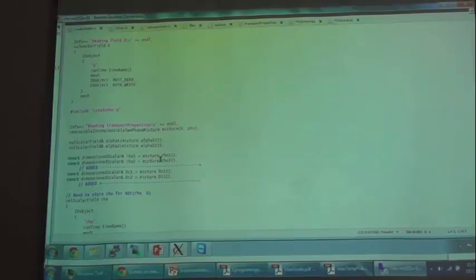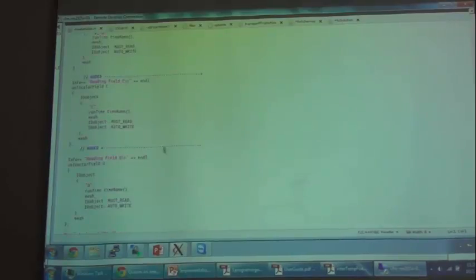So these are the properties that you have to basically add to the existing solver. It would already have provision to access rho 1 and rho 2, which is the density of the individual phases, and you just make these additions. And another thing that you have to add is a provision for creation of a separate scalar field for the C variable.